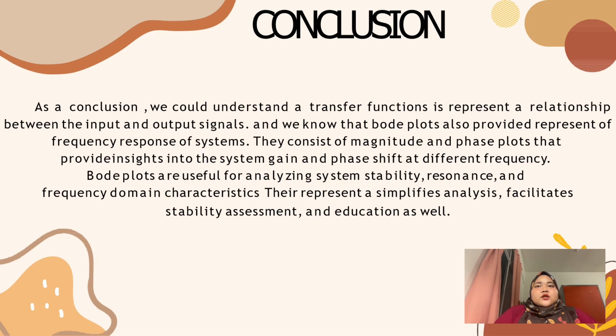To sum up overall, we understand that a transfer function represents the relationship between the input and output signal. And we know that Bode plots represent the frequency response of a system. They consist of magnitude and phase plots that provide insight into the system gain and phase shift at different frequencies. Bode plots are useful for analyzing stability, resonance, and frequency domain characteristics. They offer simplified analysis, facilitate stability assessment, and are educational as well.